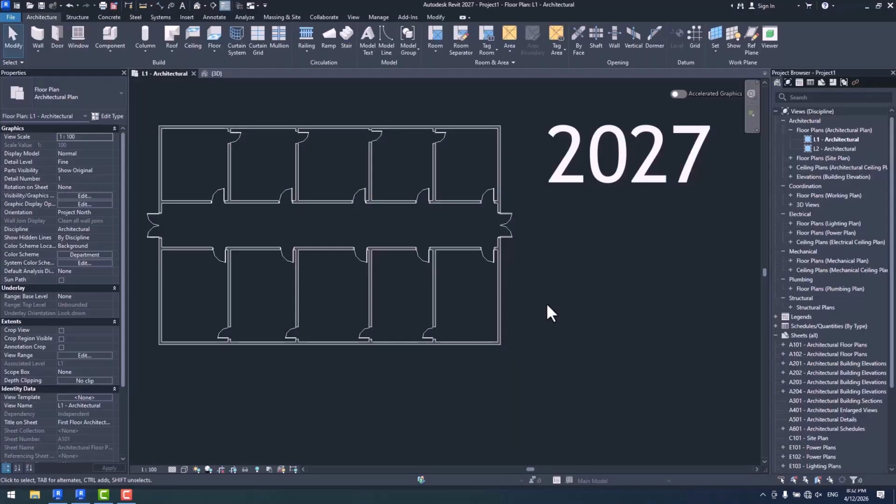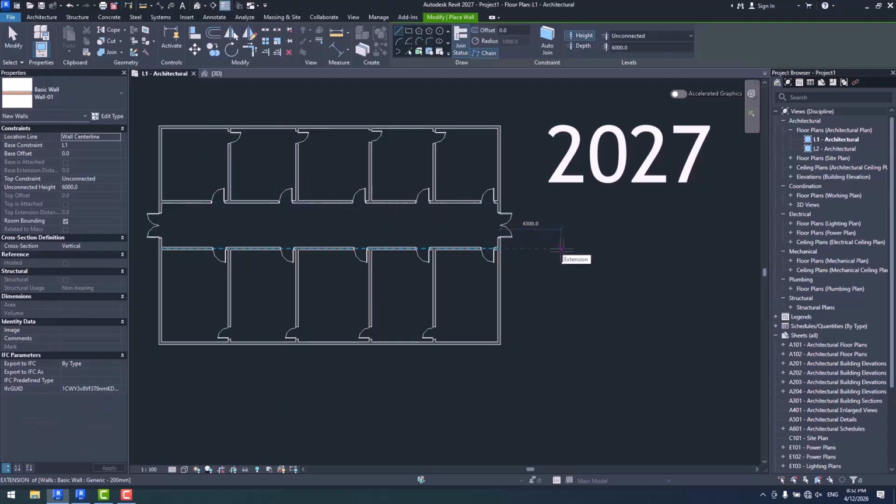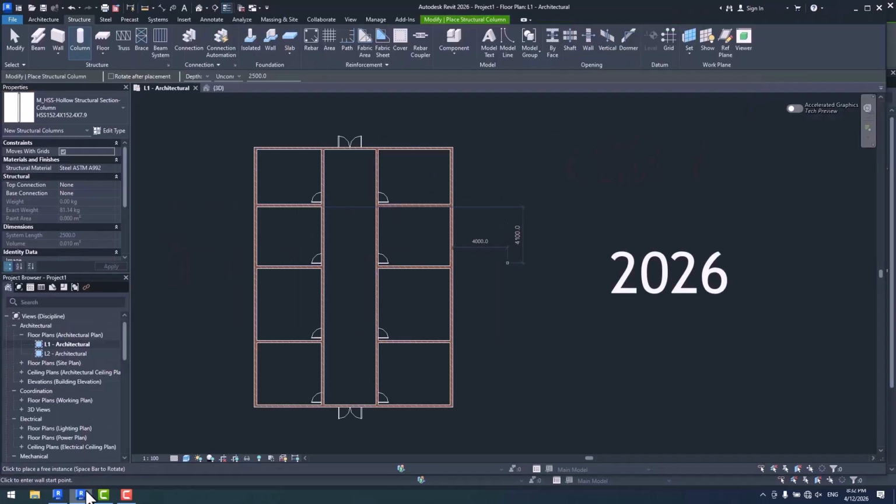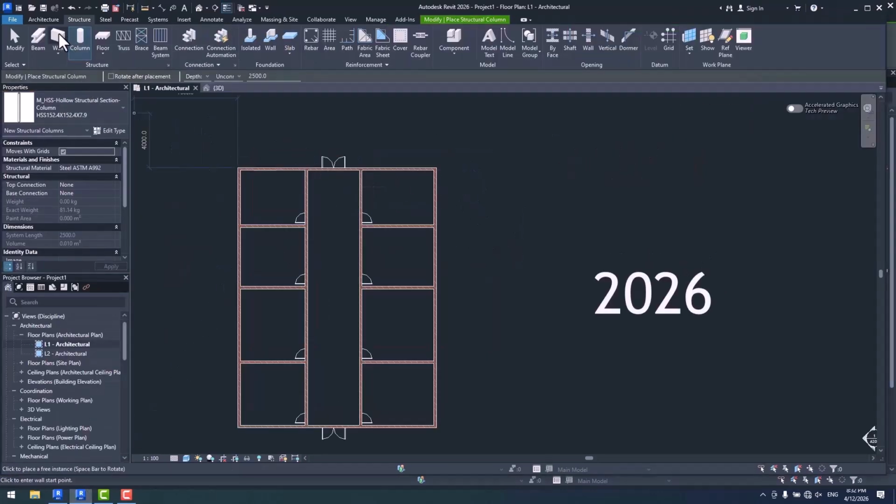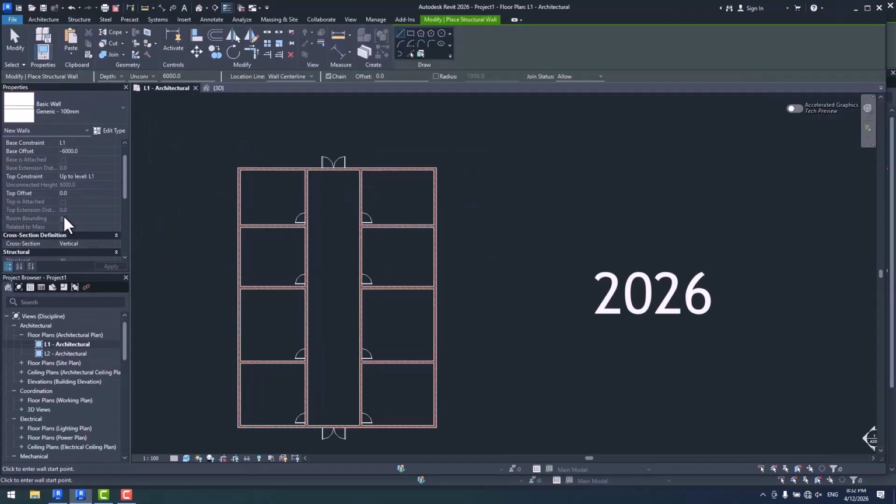Today, we're going to talk about walls. Now, to put it simply, we're going to talk about some new features as well as some changed ones. Now, as for our first point, guys, in Revit 27, before we begin setting the walls, we would be able to control the room bounding option. If you recall, this wasn't really possible back in prior versions. Like in Revit 26, we had to set the walls, then control this option.